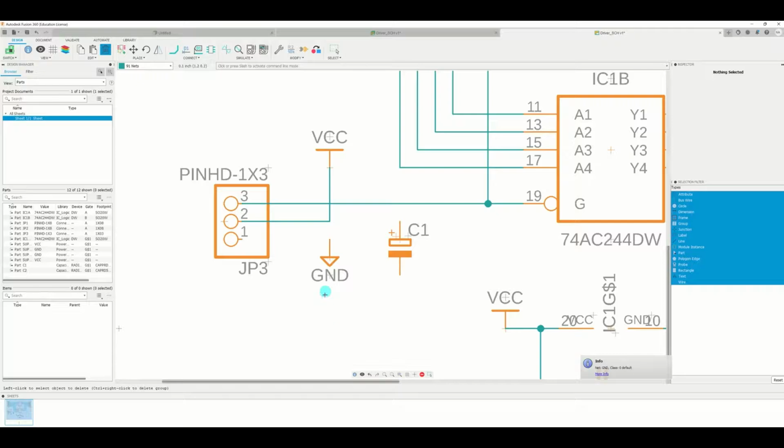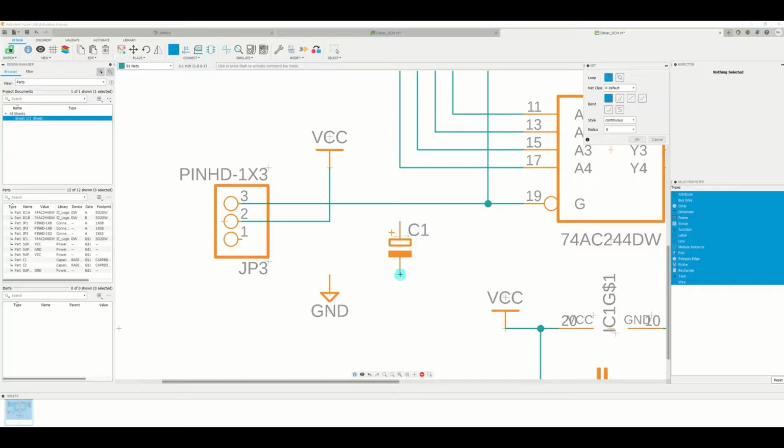Okay, then you move this down, click the component. Sorry, we have deleted the group, the whole thing. We can undo it here. So that's it. Then move it, then click the handle, and then move it down until this is aligned. Okay, then we select connect the net, click here, connect, and then click this one, and then connect, and then we connect this to this one.